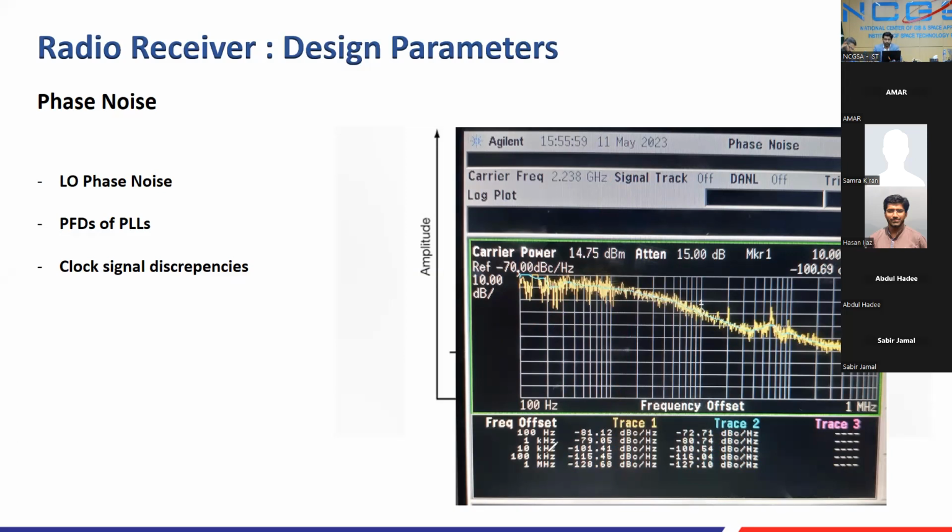You can see in this section that there is a carrier. Then you offset from that 100 hertz, then 1 kilohertz, then 10 kilohertz, 100 kilohertz, and 1 megahertz. These deviations are standard. For any local oscillator, any PLDRO, any dielectric resonator oscillator, any Gunn diode oscillator, you will find the phase noise power of the carrier at these offsets. This is a standard: 100 hertz, 1 kilohertz, 10, 100 and 1 mega. So you can see as you move away from the carrier, the skirt falls.